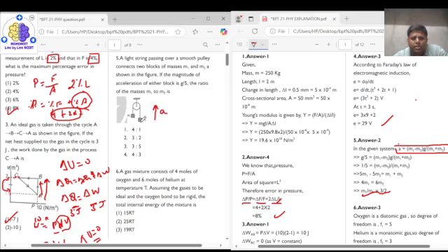This is the acceleration. So we're drawing the free body diagram for, let's say, m2. For m2, here we have tension and here we have m2 g, its weight, and still it is accelerating in this direction. So we can write that T minus m2 g is equal to m2 into a, right?